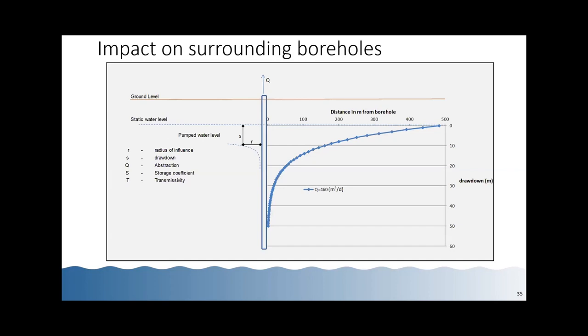Okay, so this is an either-or situation: if we have monitoring boreholes for the test pumping period, where they were observed for the test, we can get quite good aquifer characteristics. And from that, we can use groundwater flow equations to look at whether we expect to impact other surrounding boreholes or not. This can be very important in the case of a farm that has a borehole near the boundary of the farm, and the neighboring farm decides to put a borehole on their farm that's close to that one. That can be a potential source of conflict between the two groundwater users.